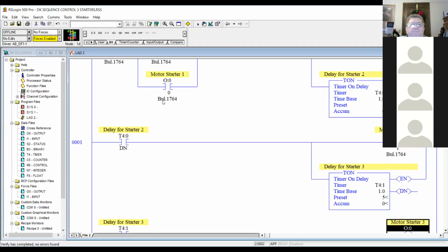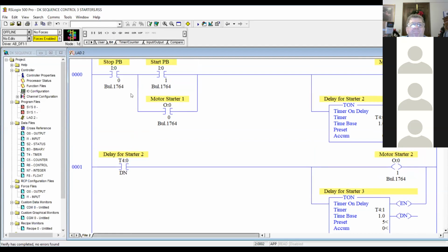Because the Studio 5000 doesn't. Right. The inputs also show it. Yeah, I see that now. The only ones that don't are the DNs. Right. They're internal. And your timers. All of your internal bits like that are kind of like base tags in Studio 5000. Things that don't have real physical addresses are internal.